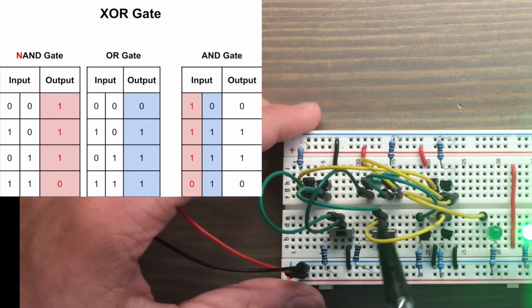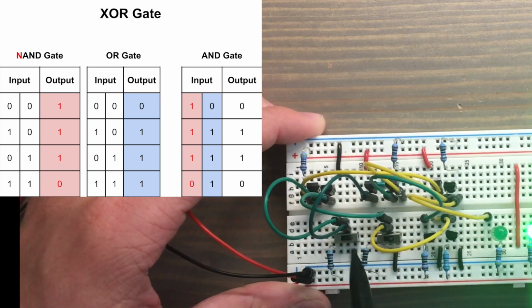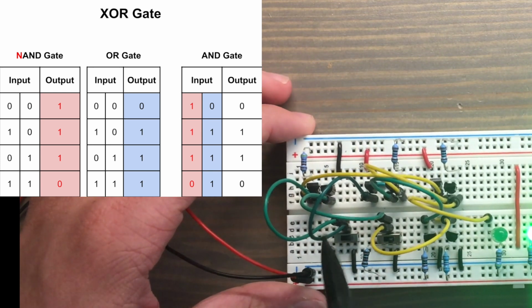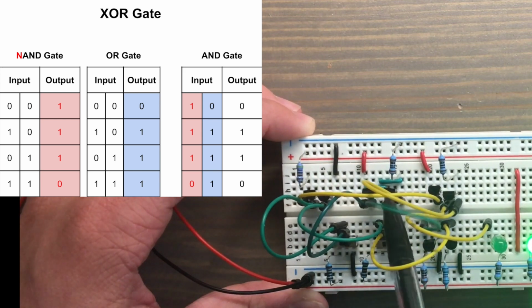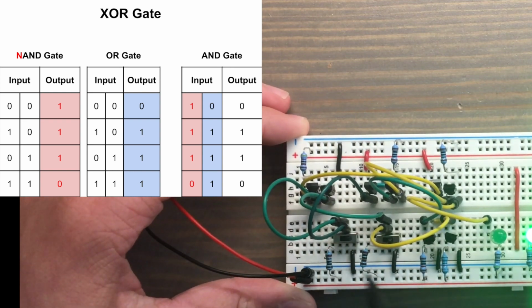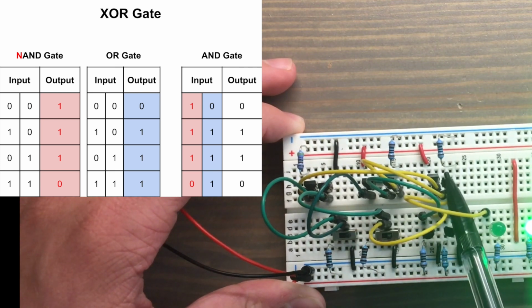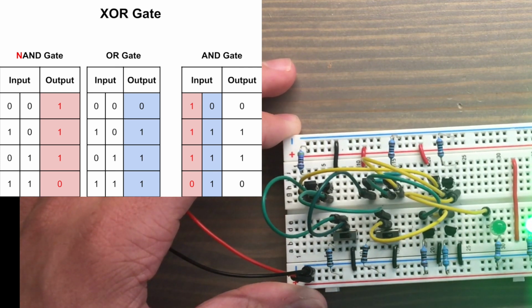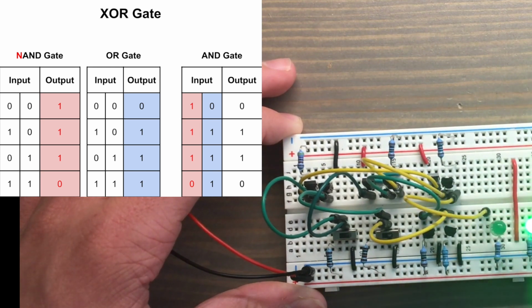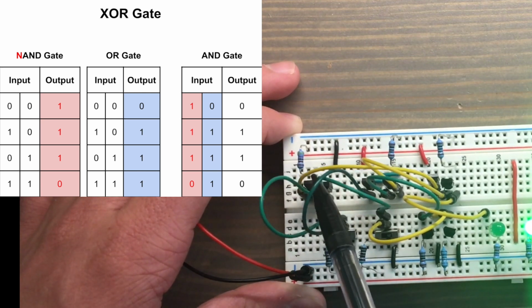This XOR gate is made up of an OR gate, a NAND gate, and an AND gate. And each of these inputs is fed into both the NAND gate and the OR gate. So the OR gate takes care of making sure that the OR gate's requirements are met. So if either one of these outputs is on, or both of them, this output will be on going to the AND gate. But this AND gate will only have its output powered if the NAND gate over here is also powered.